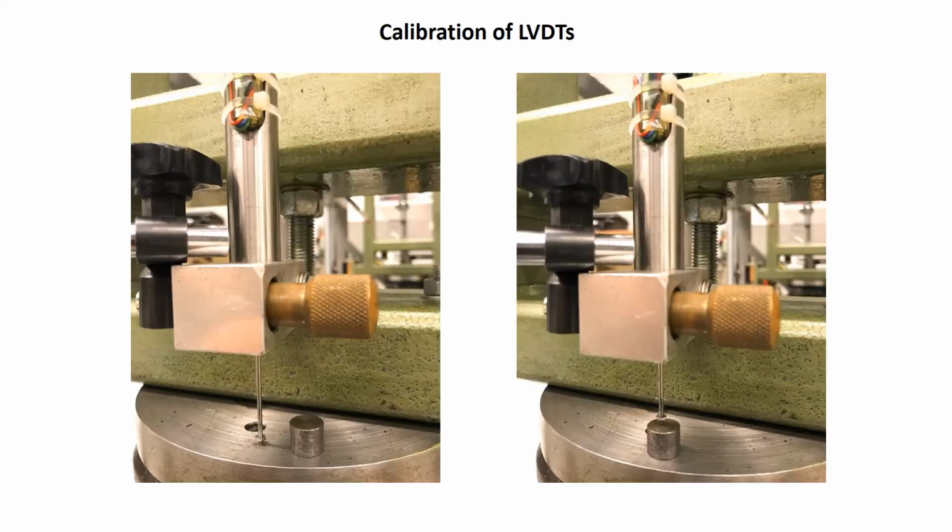To find the sensitivities of LVDTs and basically to convert from measured raw voltages to engineering units, we can statically calibrate the LVDTs. So basically, we use a gauge block and put it underneath the LVDTs, and we measure the produced output voltage.